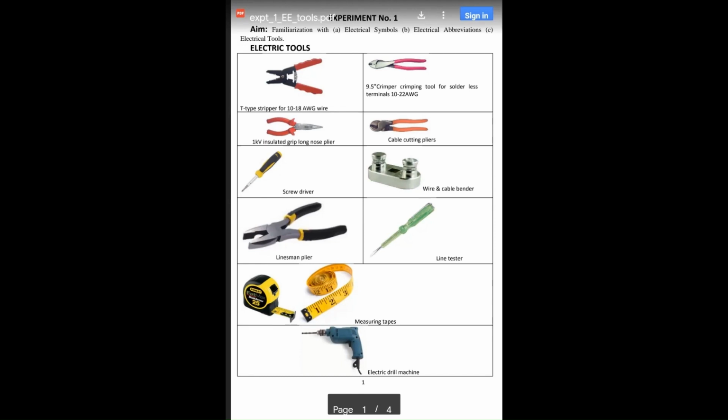The appliances associated with these power plugs are generally single phase AC or microwave. Although for AC connection you can also use MCBs. The rest of the plugs, used for an electric kettle or mixie or charging points of our mobiles, all use 5 amperes.